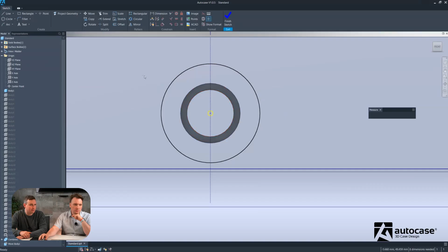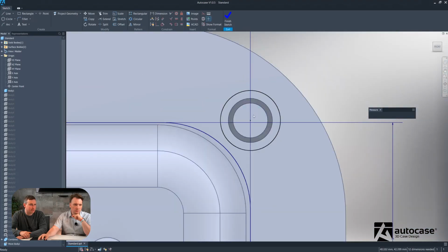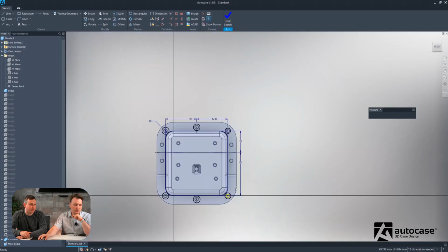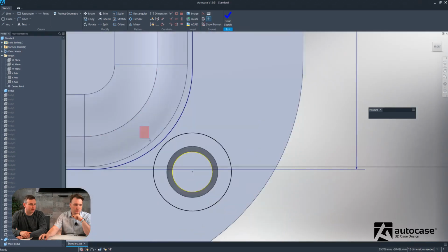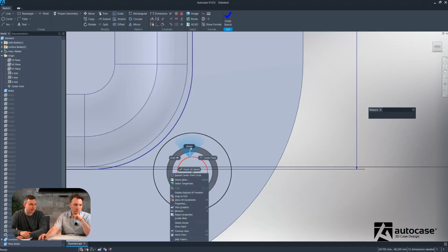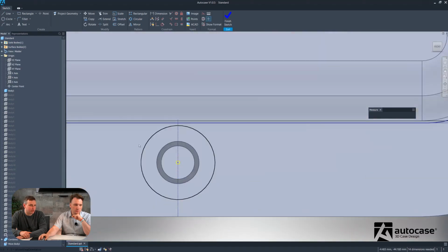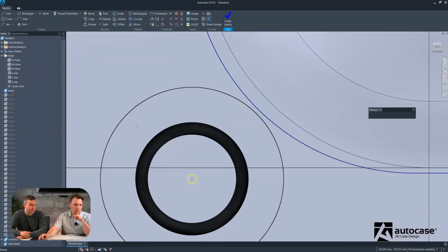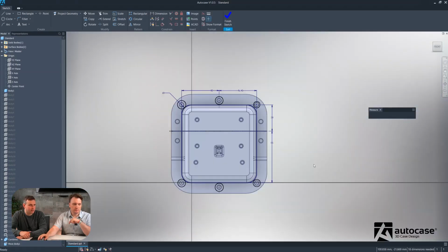Yeah, let's just do that same function there. And then delete, just making sure there's no additional geometry on the sketch of the whole cutout. And we're doing a left to right drag, which is ensuring we're only selecting geometry that's within the box that we've drawn. Final hole. So we've now cleaned up the geometry, and we can now resize all of our drill holes.